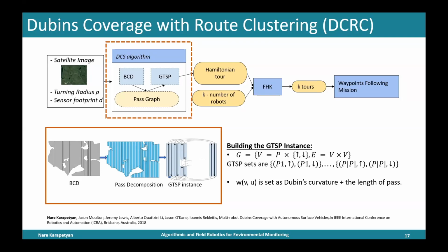So now it is a set of different cells that do not contain any obstacles. The path generation performs the following. For each of these cells, it will split the area into strips that have a width equal to the sensor footprint. If the robot moves along a path, it will completely cover a single strip.